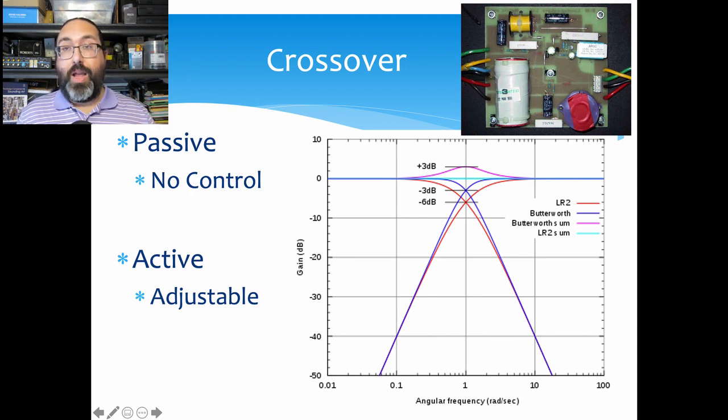And you are able to control each because you have a crossover somewhere. Normally it's inside the amp now, but it used to be a separate processing unit, and you're able to control where that crossover point is. So where the low speaker has frequencies that it's sending, and that high speaker has frequencies that it's sending. You can do some cool things if you biamp a speaker.